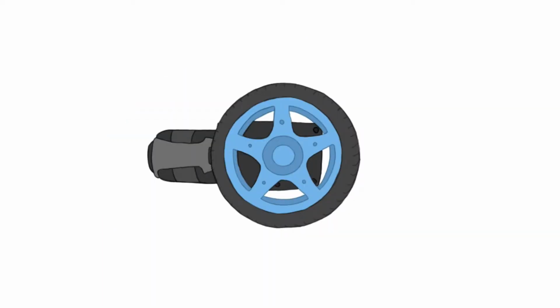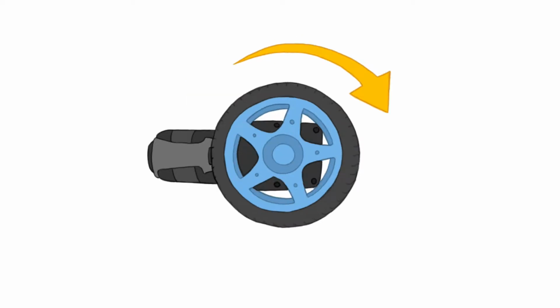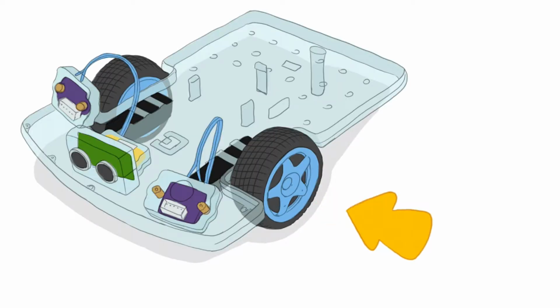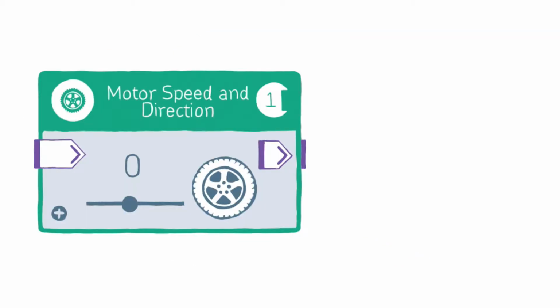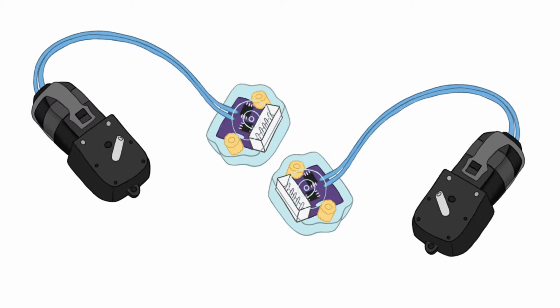Some blocks specify that the motors can move forwards and backwards, but remember that this is based on their orientation while attached to the racer chassis. Also, when using this smartware, remember that each block from the smartware menus will have a number in the top right corner that signifies which port that particular block came from. If you are using multiple DC motors, keep track of which ports the blocks you are using are from.